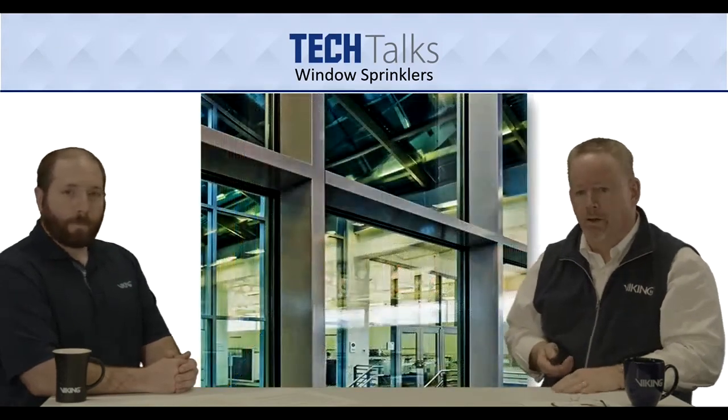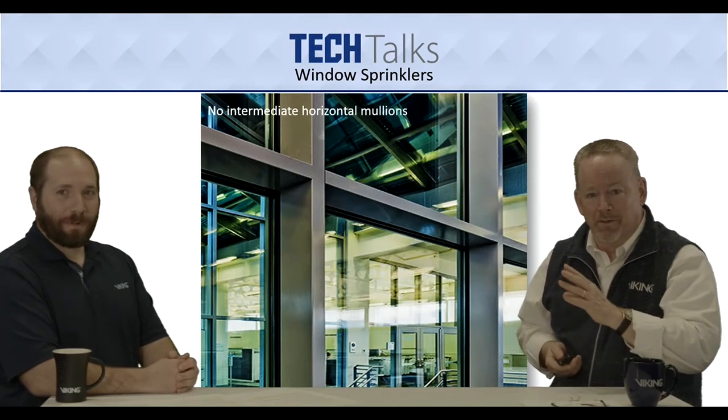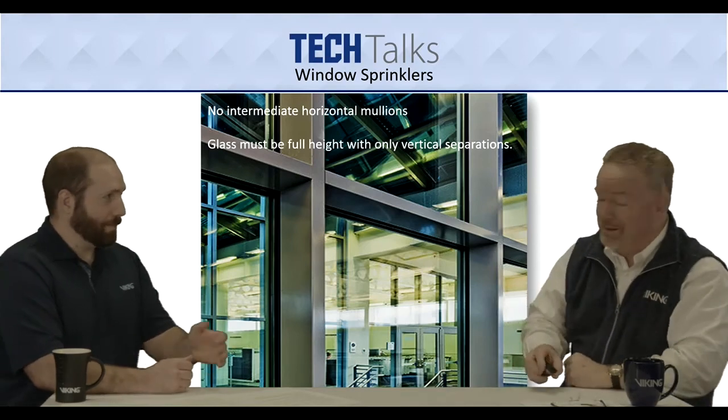All right. Now, mullions. Let's talk a little bit about mullions. The only ones that are permitted are vertical mullions. The obvious challenge is if you have a horizontal mullion, that's going to stop everything. So I guess if I had a horizontal mullion, I would wind up with another sprinkler down below it? No, actually, that's not allowed. You have to have a single level, so no horizontal mullions. If you happen to have a horizontal mullion, that bottom glass either has to be fire rated, so it's going to be a little bit more expensive glass, or you create a pony wall, or you lose some of that light.